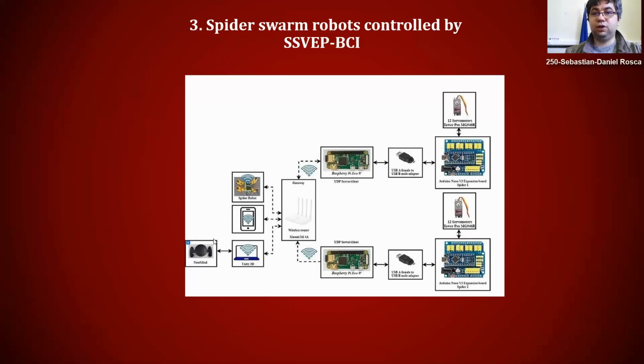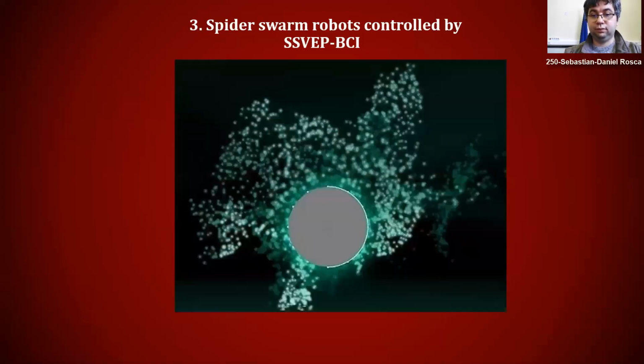As a BCI solution, we use NextMind BCI headset to acquire EEG signals of the user because it provides nine patented dry active electrodes placed in accordance with the International 10-20 EEG system adapted to measure the brain activity from the visual cortex. In next figure is presented the interface of calibration manager provided by NextMind SDK that we implemented in our solution to measure the user attention level obtained as response of the visual stimuli to be used as reference for active control.